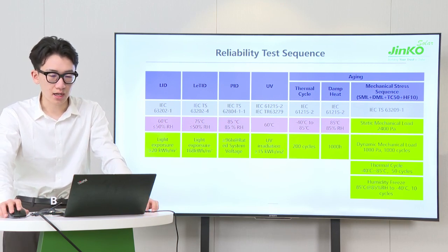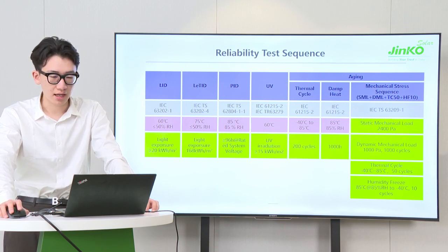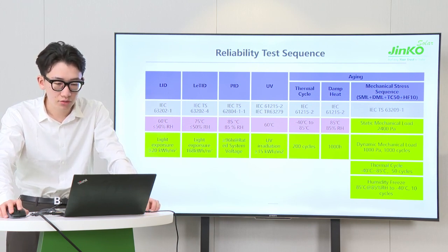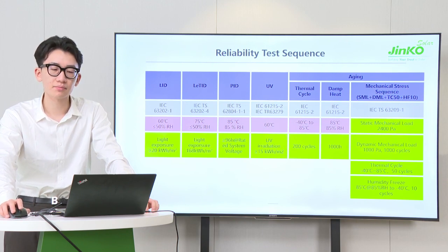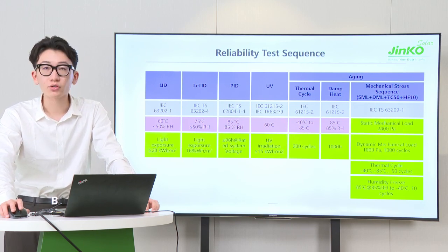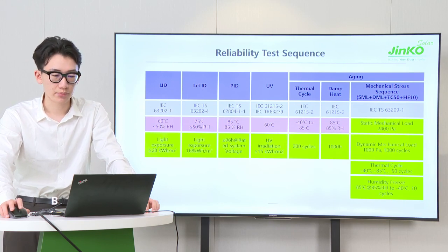However, based on laboratory conditions, newly produced N-type cells have characteristics such as zero or even negative degradation. So when the purpose of the test is to observe LID performance, the test may be continued beyond 20 kWh per square meter. In the LETID test, the module is exposed to an irradiance of 1000 watts per square meter.